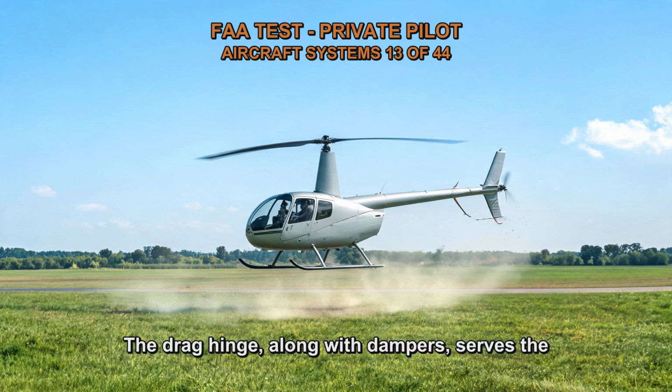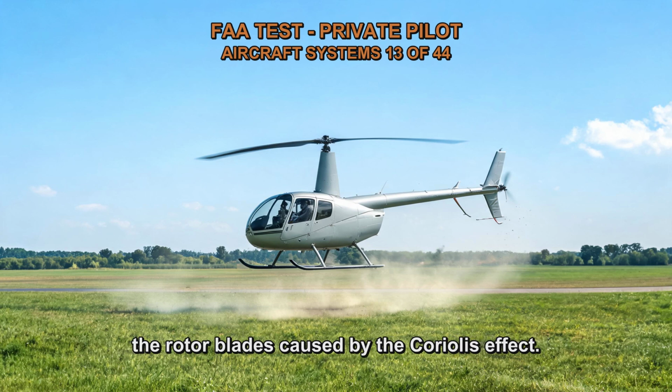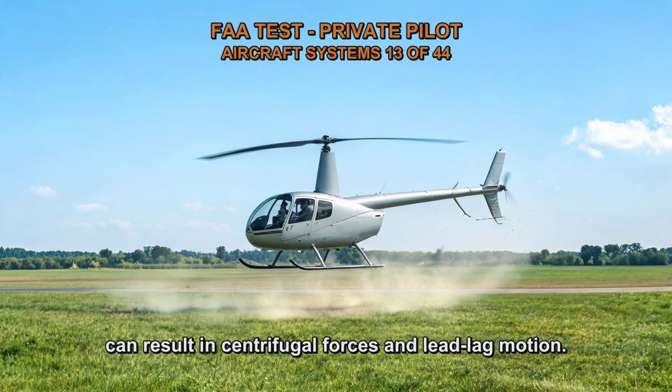The drag hinge, along with dampers, serves the purpose of absorbing the acceleration and deceleration of the rotor blades caused by the Coriolis effect. The Coriolis effect is a phenomenon that occurs due to the rotation of the rotor disc. As the blades rotate, the changing velocity of the blades in relation to the rotating disc can result in centrifugal forces and lead lag motion.